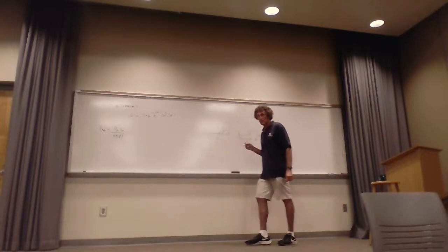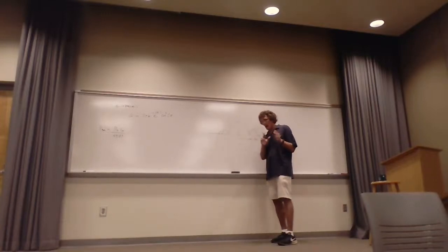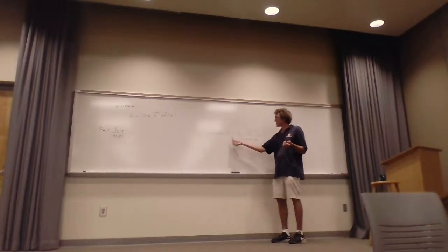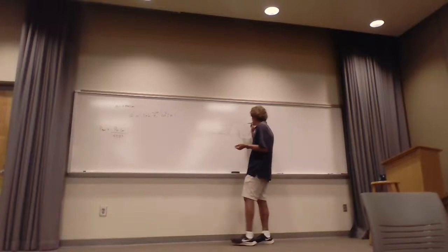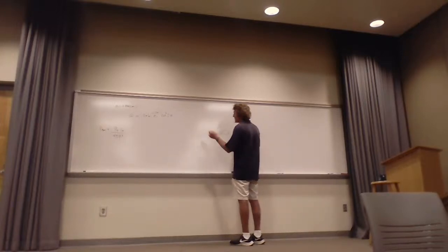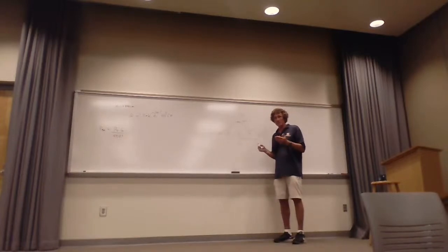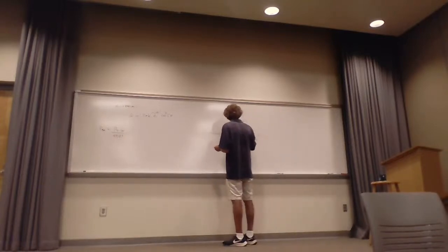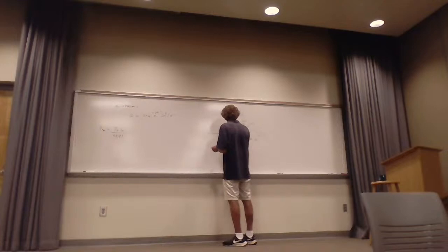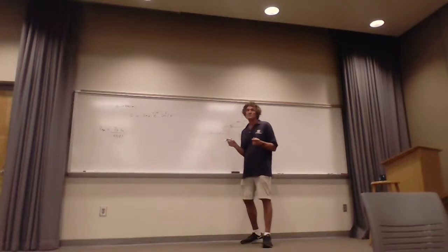Right? Y'all agree? So the half power beam width, there's a null to null. And the null to null, you just find this one. Right? And this would be the gain. And the peak value here would be at 0, it would be 20K, right? Whatever that is, I didn't give you a K. So the beam width itself, you would have to find the point where it goes to half that, where it goes to 10K here, and down here, and 10K here, right? And you'd have to find that width. How would you do it?